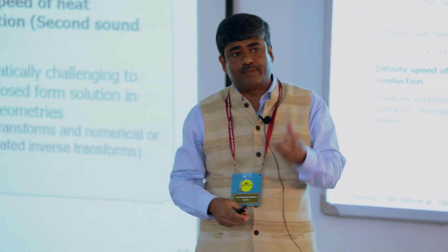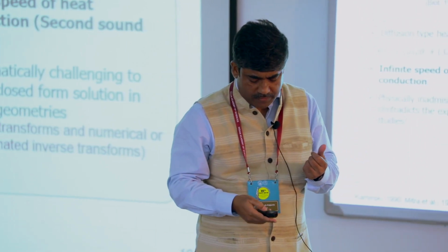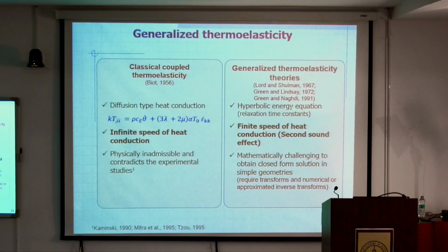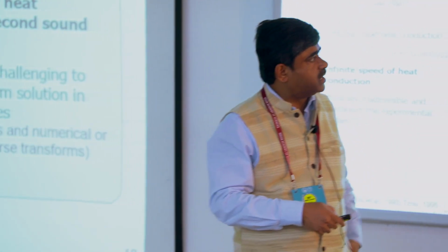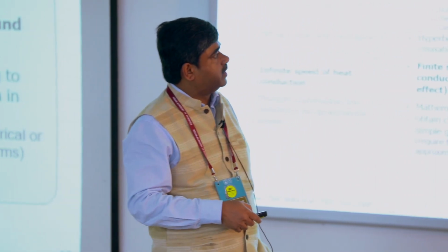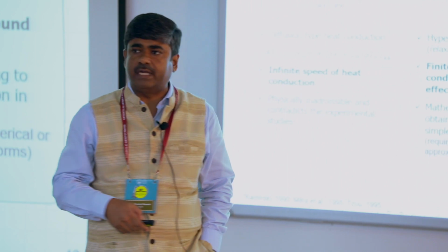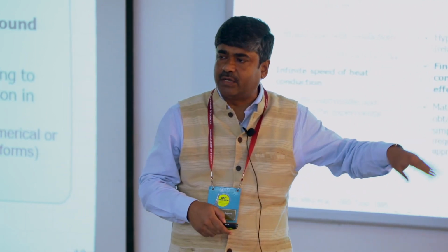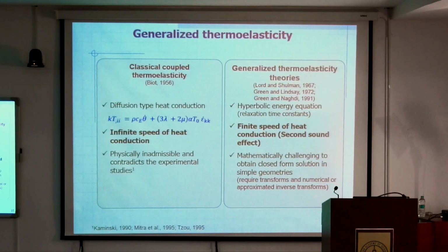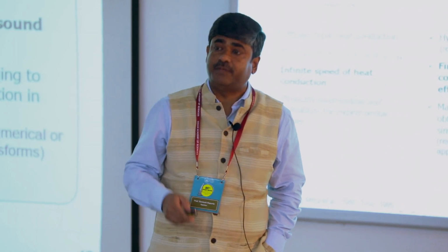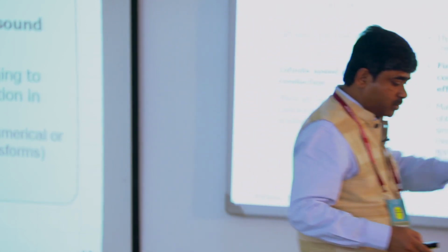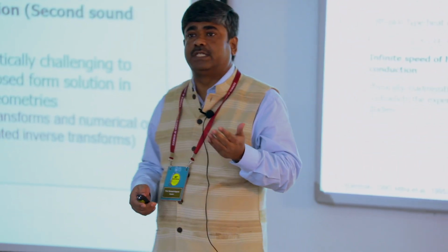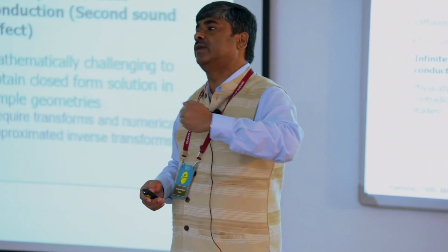So to capture that physics, finite speed of heat conduction, there have been different kinds of generalized thermoelasticity theories like Lord-Shulman, Green-Lindsay and all that. What we have done is use these theories for our analysis of the thermal shock problem, so that we can capture the second sound effect, which gives very interesting phenomena. In fact, this gives rise to very sharp wave fronts, which are not there in classical thermoelasticity, and those sharp wave fronts are again very difficult to predict.